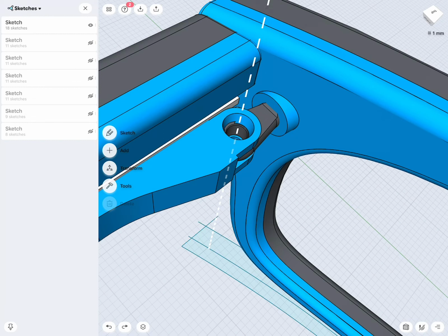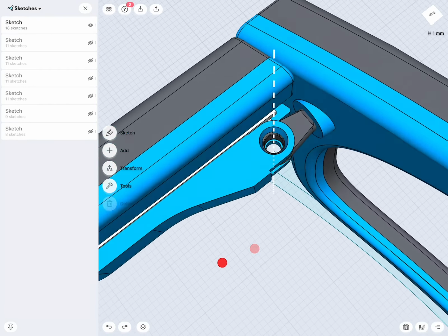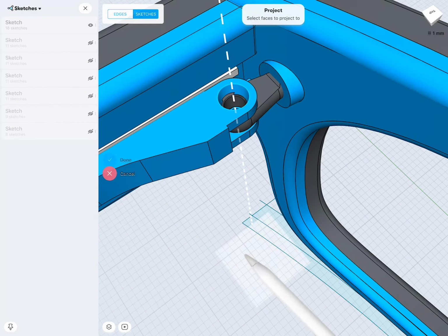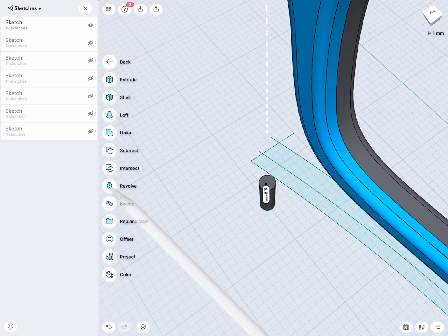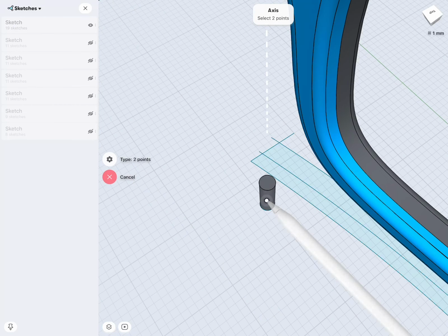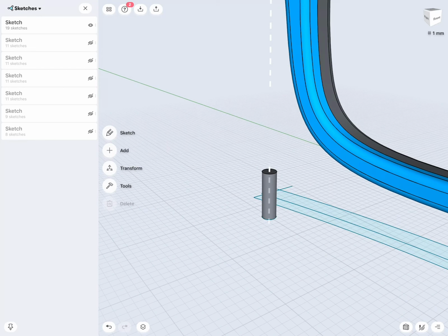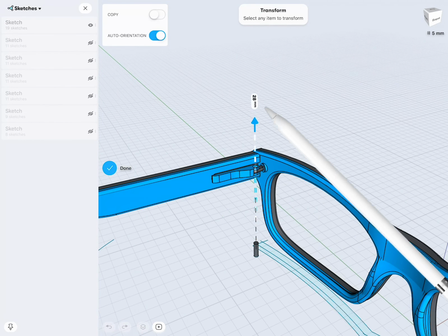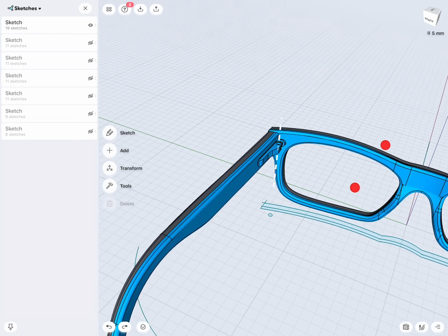In case something like this doesn't necessarily work, we can also do a simple workaround. If, for example, that's not a perfect circle, on the sketch I would project the profile of that arc. So check this out. You go Tools, Project, select this ring, next, select the sketch, done, there's our ring. Now this ring I could extrude up and then add an axis through there, and this axis, via the move command or transform first, I can scale and then move up to where I need it. So super easy. That's the way I did this.